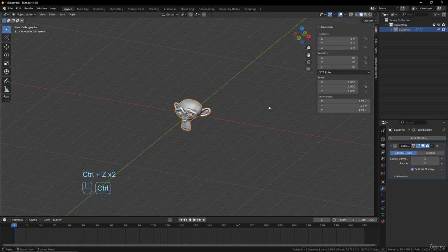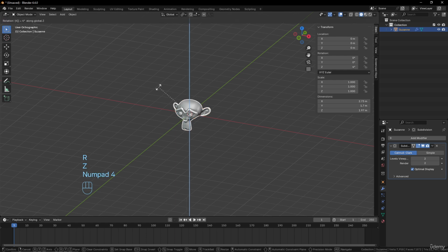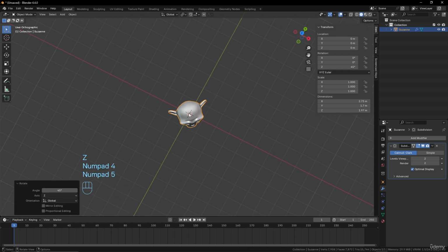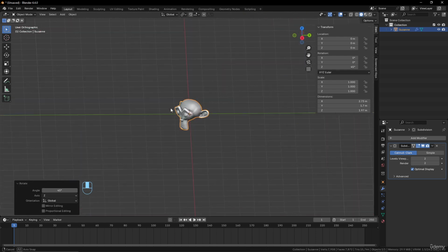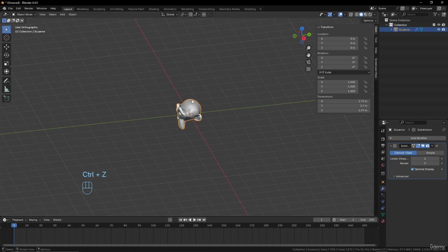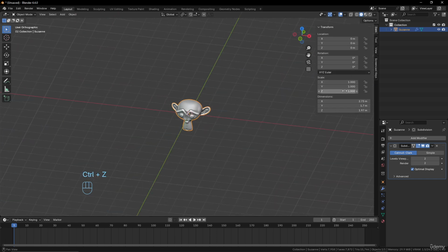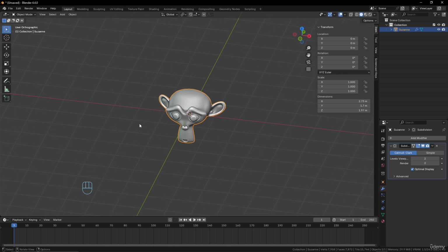It can be very useful to add some values, or maybe you want to play with rotations, you use the degrees here. So if you make RZ 45 degrees, it will move 45 degrees on the z-axis. Rotate, sorry, not move. And here you have the scale. For the scale, you can just remember that the basic object is 1, okay?